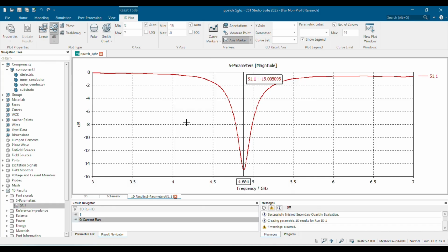Now we need to improve our resonant frequency as well as our return loss. For that we will reduce the r value in order to get a closer frequency, since the radius is inversely proportional to the frequency. We'll also tweak the distance of our coaxial feed line.